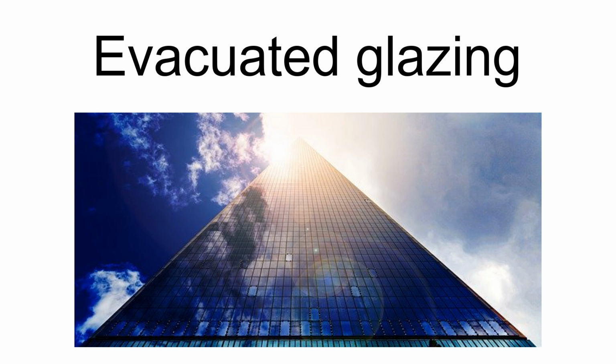Unfortunately, evacuated glazing does have some disadvantages. Its manufacture is complicated and difficult. For example, a necessary stage in the manufacture of evacuated glazing is outgassing, that is, heating it to liberate any gases absorbed on the inner surfaces, which could otherwise later escape and destroy the vacuum. This heating process currently means that evacuated glazing cannot be toughened or heat strengthened. If an evacuated safety glass is required, the glass must be laminated.